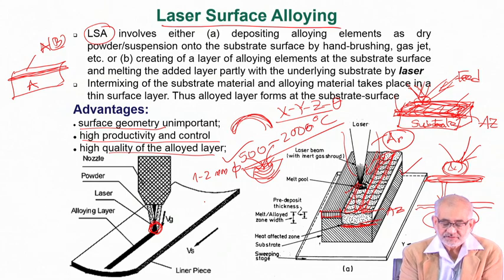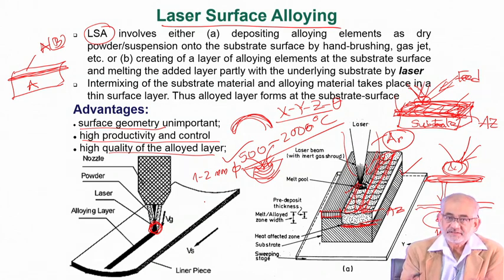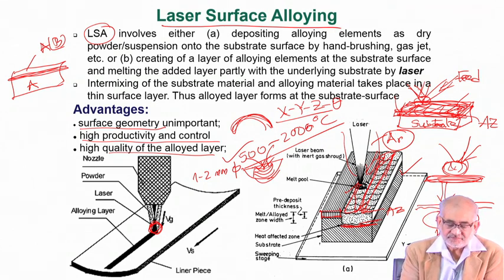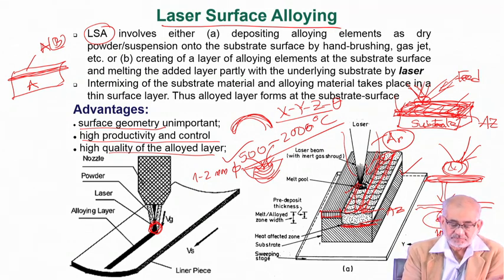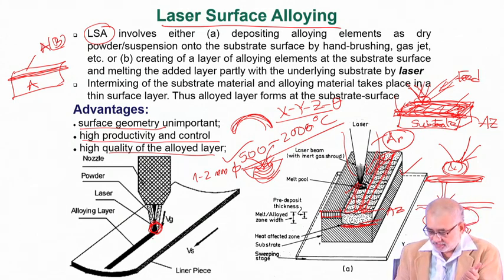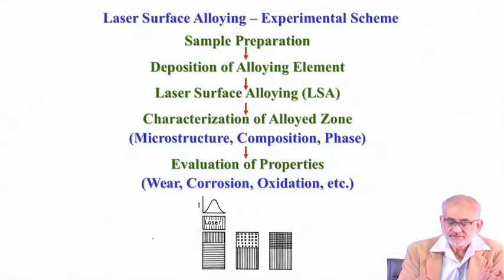Compared to this, if you subject this whole component to one single isothermal chamber and then take it out, there will be a lot of scope of expansion and contraction, leading to thermal stresses and distortion. That level of distortion can be avoided to a large extent. Okay. One important thing, let's go to the next view graph and then it becomes easier.